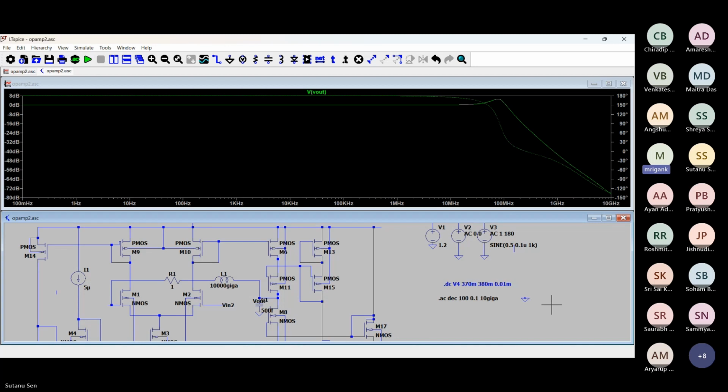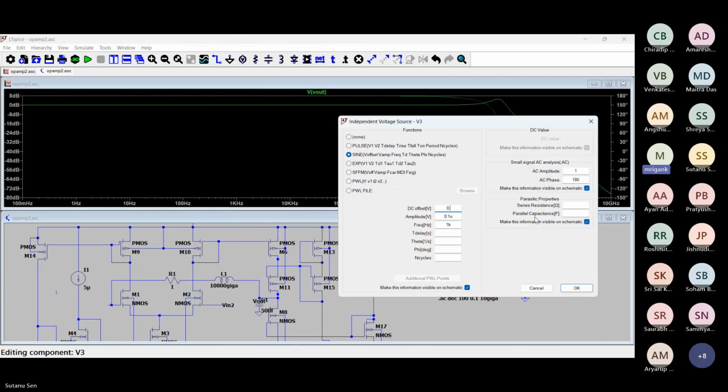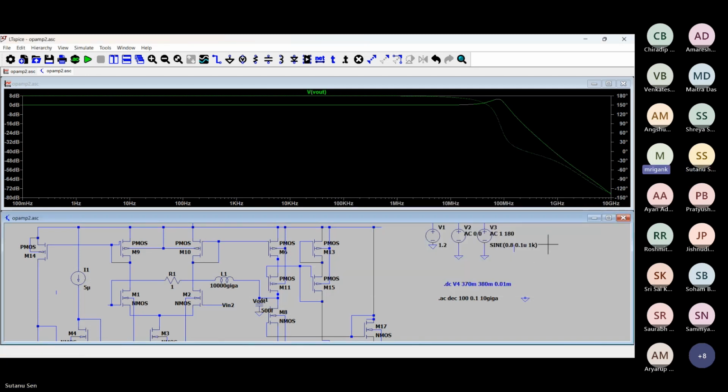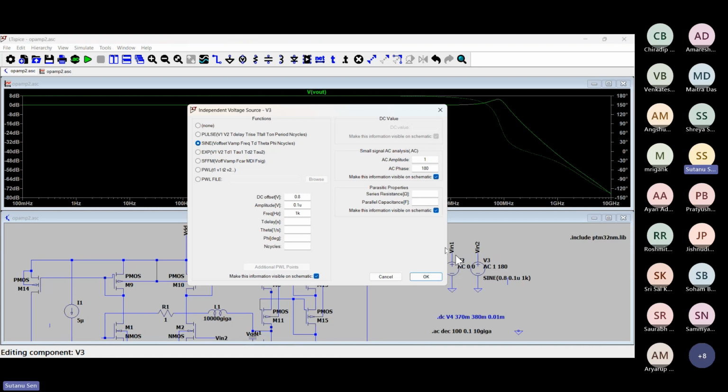And L, C is here. Can we, the DC gain, AC point of view, shorted, open circuited, but still not getting anything. Output DC, you check, output DC is coming properly. Output DC anyway we saw, so that was coming properly. Yeah, but AC gain is not coming. Although it is an ideal L, and omega L should be very high, even for 100 hertz, but that's not coming. I've increased it already to 1 kilohertz.